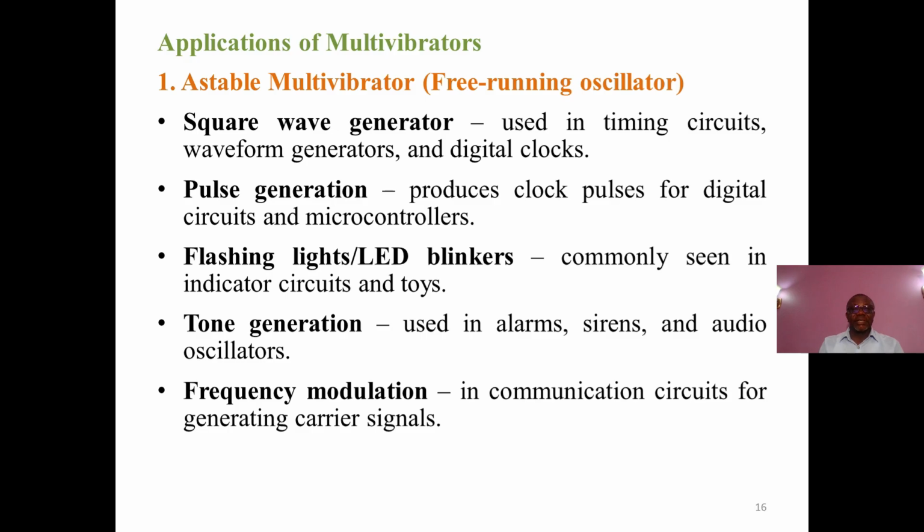So it is these astable multivibrators or the free-running oscillator that you make use of. We also use it for flashing of lights, LED blinkers, which you see in toys. Also for tone generation used in alarms, sirens, and audio oscillators. Frequency modulation in communication circuits for generating carrier signals.